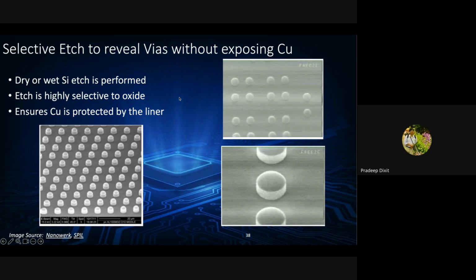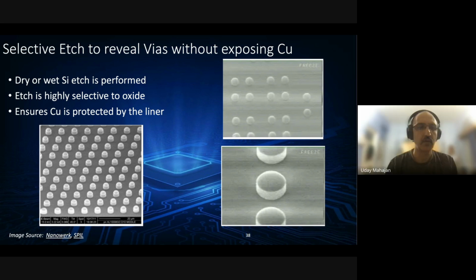So this is a very critical process. And controlling the height of these pillars, the uniformity, is extremely critical. And that height variation essentially is the sum of the etch variation, the wafer thinning itself, and of course the original variation of the TSV trenches themselves when they were formed at the beginning of the via metal process.